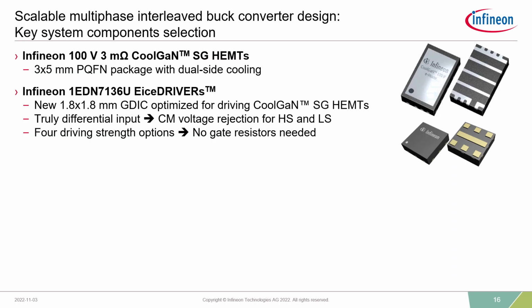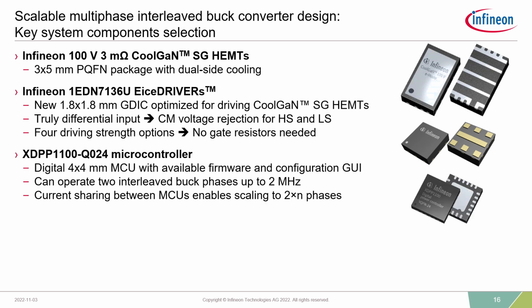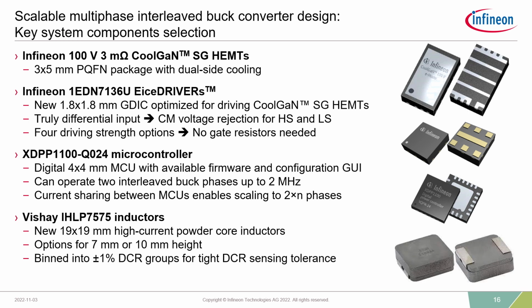We start with the transistors and the drivers, but this isn't the entirety of the DC-DC converter. We also have to consider the microcontroller. In this case, I'm using a microcontroller that can very easily drive 2 interleaved buck phases, and the controllers themselves can be synchronized to parallel multiple phases in pairs. Then we have to consider the inductors.